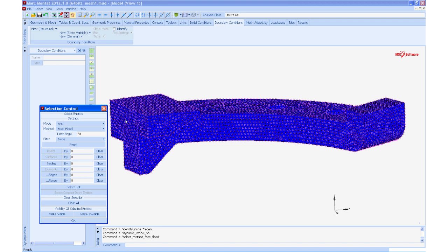So you can see, for example, over here, if we select let's say a node, we can select everything on this face, and here the angle is about 90 degrees around this region, so it won't be selecting anything over that. So let's say I want to select all the nodes here on this particular face. So let me click on nodes, and I click on one node, and as you can see, it went ahead and selected every single node, because that is the method that we had chosen. So it is quite simple to select everything here.